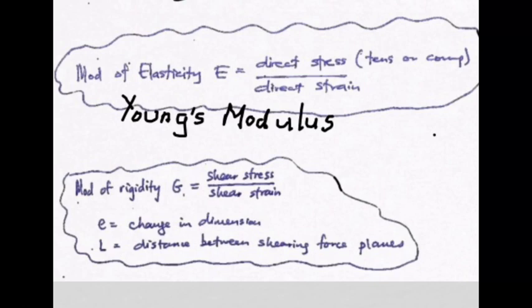Okay, now in a very similar fashion, but not to do with direct tension or compression, if you are selecting a material based on its shear strength properties, you'll be working with a very similar quantity called modulus of rigidity, denoted with capital letter G, where it would also be the stress over the strain, but in this case it would be the shear stress over the shear strain.